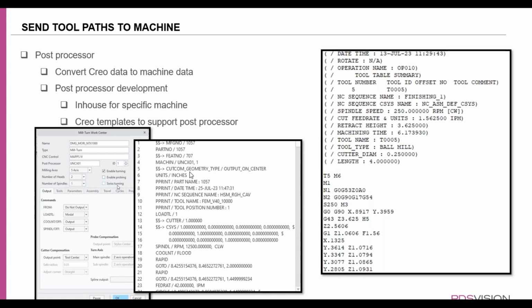And each machine is different. There are certain M codes and certain G codes and things like that that need to be activated. And then on top of that, there's user preference as well. So some customers might want the spindle command, the S, on a single line, or they want it with the first or just before the X, Y movements, and then after Z, or something like that. So it makes it easier to read for the machinists, and it makes it easier to check.